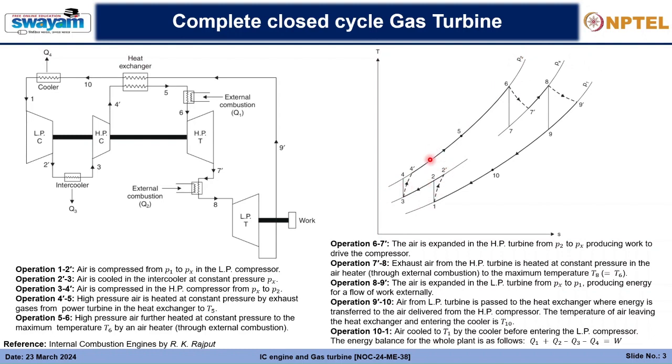But even if we have gone towards this side, the net amount of work that needs to be done to compensate for this would be very high, and the intercooling is actually lowering the net work input to the compressor. That's why we need this two compressor arrangement. Sometimes it can be a three compressor arrangement as well. So we'll have to see what our pressure difference is, and accordingly decide how many stages we will have to use. And there is an intercooler which will cool down the fluid which is flowing throughout the cycle.